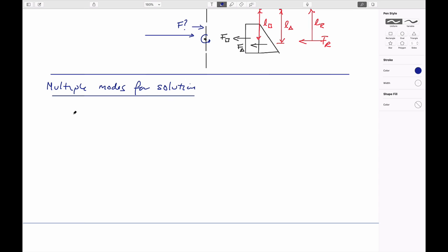We drew up at the top the way of calculating the magnitude of the force and where it acts by using this kind of approach just at the top of this page. So we've seen this already. Define the centroid within the plane. That allows us to calculate the force as area times unit weight times the depth of the centroid.